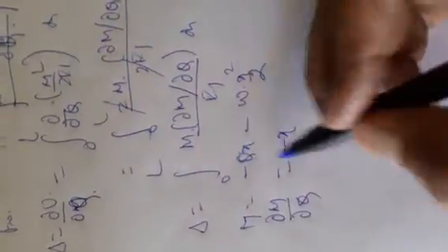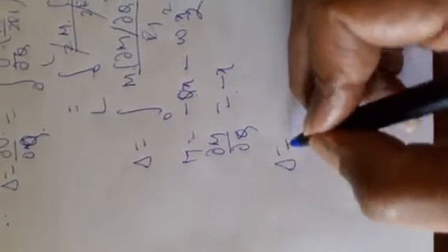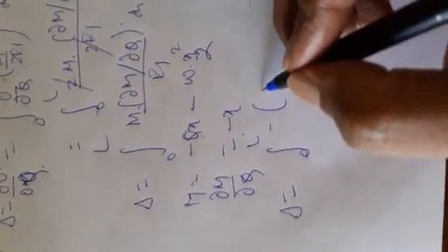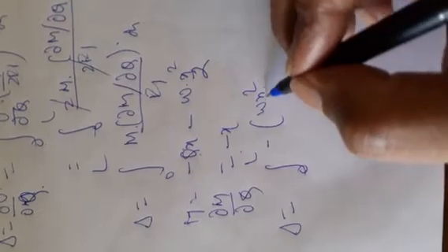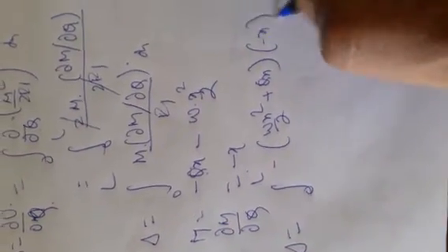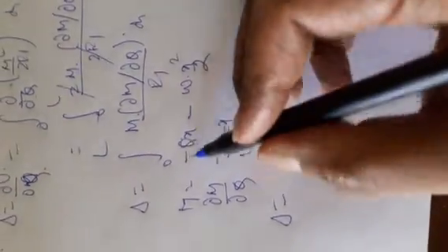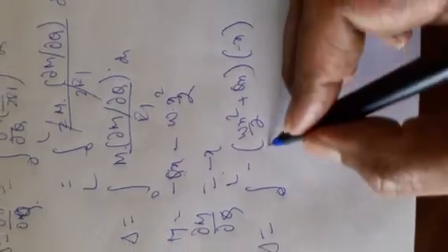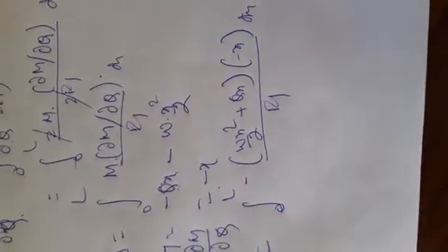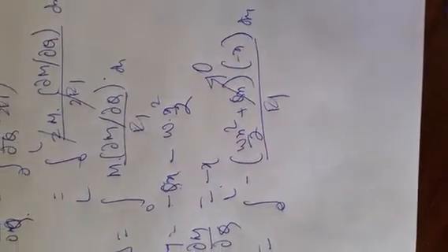So substitute M and dou M by dou Q in this equation. Therefore delta is equal to integral 0 to L of minus of Wx square by 2 plus Qx, into minus x, divided by EI dx. Same term, Wx square by 2 plus Qx, minus I have taken it outside, into minus x divided by EI dx. Now here before integration set imaginary load to 0.